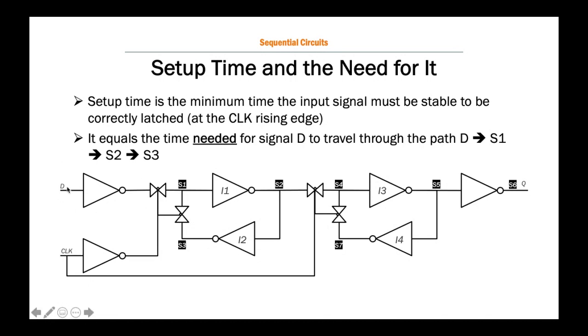So that's why we said you need to be stable at the setup time, which has this calculation. It goes a little bit more, but you get the idea. We need that setup time, which is the time for the signal to be ready when the clock comes and opens the gate, so I'm properly sampling the right value that I was looking for. This is the green path: once the gate opens, I have the right value from T minus 3 that needs to go in there.